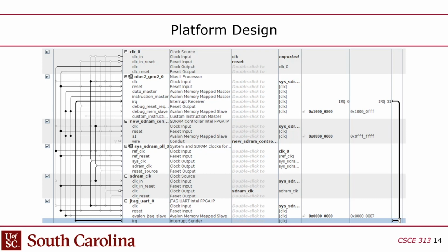But it's still multiple signals. So this one wire is kind of like having an SPI channel, essentially, where it's one channel but multiple sub-wires in there. Except with Avalon, it's a parallel bus too. It's not serial. Usually these on-chip buses are parallel, meaning it's 32 bits every cycle or 64 bits every cycle, as opposed to 1 bit.